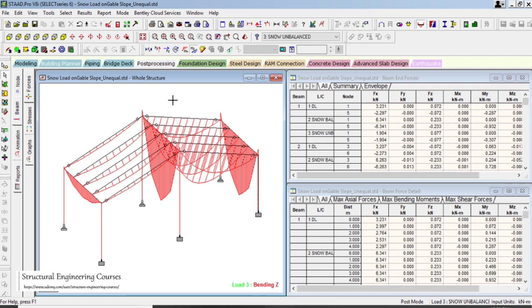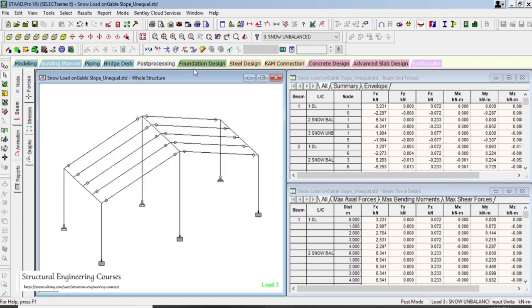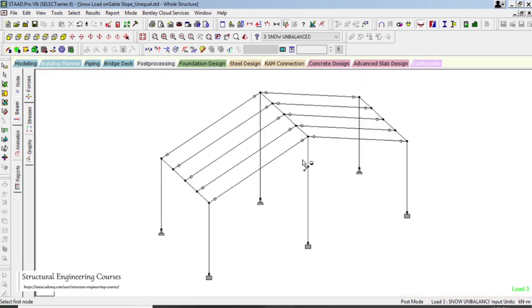And there is one more thing that you should know, that is if you are conversant with the ASCE 07 2016 code, the W, that is the width of the portal that needs to be considered. As per the ASCE, the W value should be from this point to this point, but as per the STAAD, the W that STAAD considers is this value, that is 6.325.